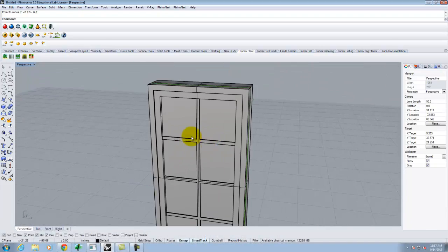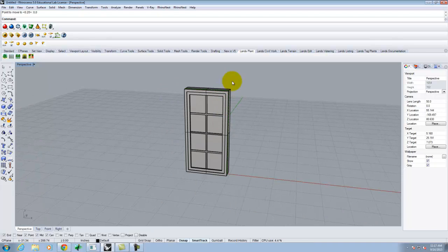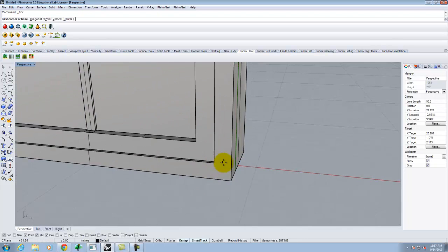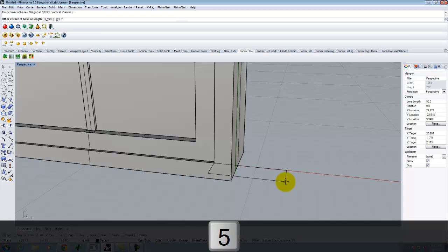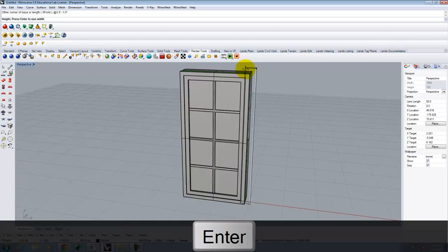Looks reasonable. Okay. The other thing is I might put trim around the window, right, thinking that this is going to go in an exterior wall, so I'll go ahead and do some exterior trim. I can use this box corner to corner. Right, we'll start right there at the corner. That's fine. And so I'll say I do 2x4 trim. It would be 3.5 inches, comma, negative 1.5 inches. And then we'll go up to the top there.